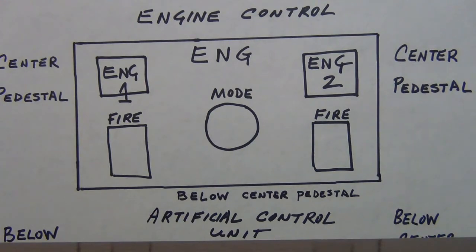Okay, all right. I do want to talk a little bit about the artificial feel unit for the throttle control, since we're on throttle. If you've worked on or opened up some of the quadrants that are underneath the control quadrants, this is no different. You've got mechanical links, so it's basically there to connect it to the engine. And again, from a pilot standpoint, I'd rather have Rick explain what happens there. But the artificial feel unit is there as a friction system, giving that load feedback to the pilot as he's controlling the thrust control levers. So that's what it's there for.